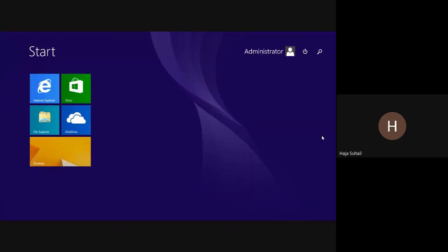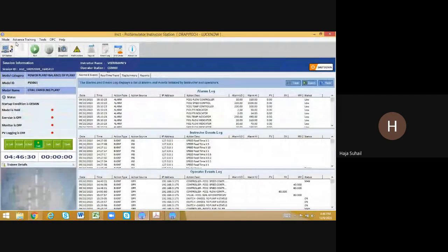Likewise, we can use the whole model center. If you are using any startup procedures in any popular model, try to use the snapshot option, because it will take time to fill some tanks, and it will take a whole day to get the steady state of the model. You can change the control to auto mode, utilizing less time, and let the controller take the steps for you. Use the snapshot option to save the particular condition file, so you can continue the next day, and you can complete the whole model within 2 days. Like that, you can plan the timeline and utilize that also.